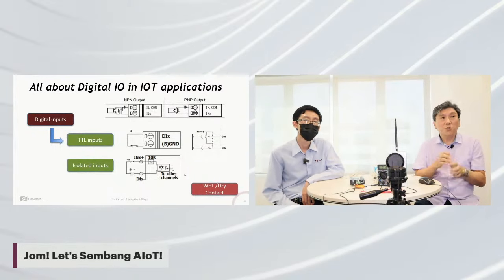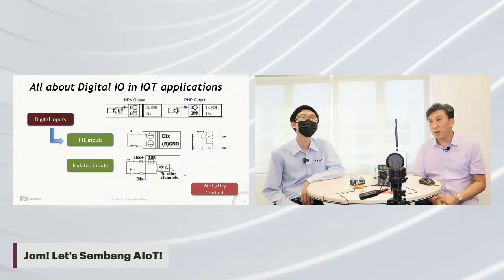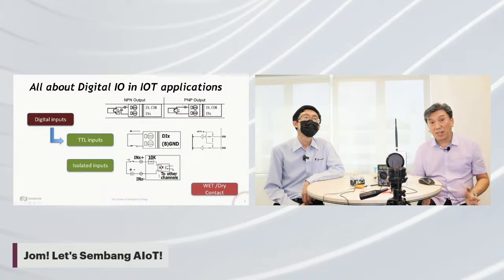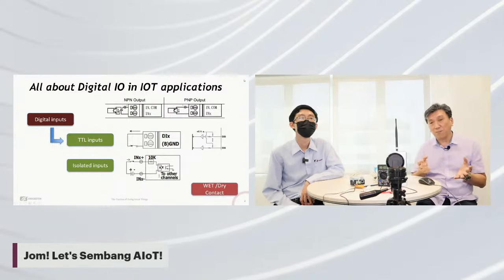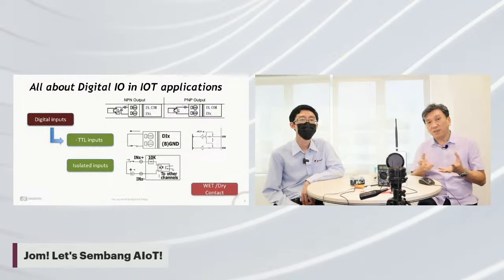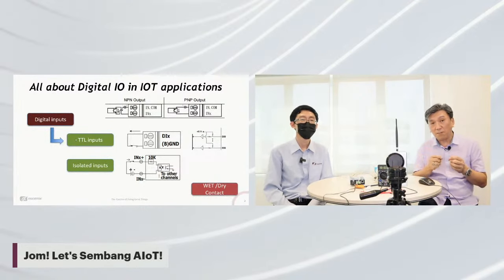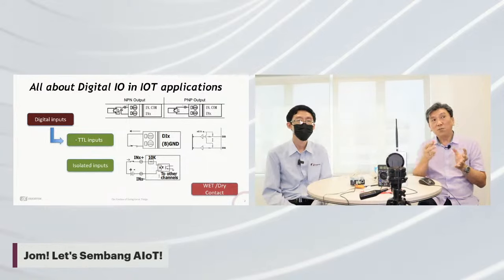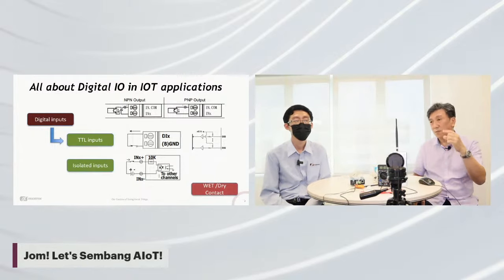In digital input, you have the NPN type or PNP. NPN is usually used by Japanese systems, which give you standard NPN. But if you go to European sensors, the contact output is in the form of PNP. So your treatment of PNP is different. NPN is basically a pull-down, from 1 to 0, but PNP is on the source side. You need a voltage to trigger it.